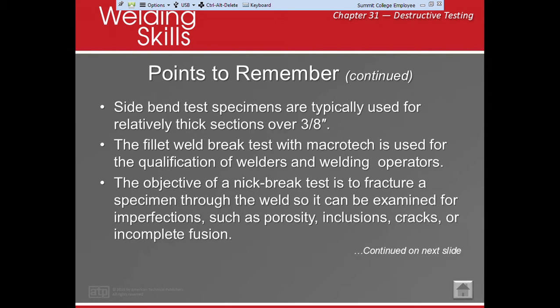Okay? The fillet weld break test with a macro etch is usually used for the qualifications of welders and welding operators. Usually, we're going to do a fillet weld break test like if we're doing a TIG qualification. The objective of a nick break test is to break it so we can look inside it for imperfections or discontinuities like porosity, inclusions, cracks, or incomplete fusion.